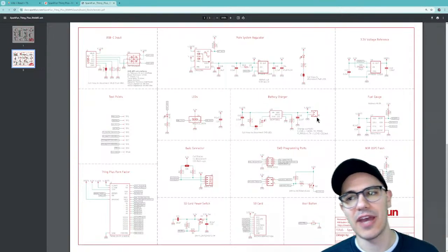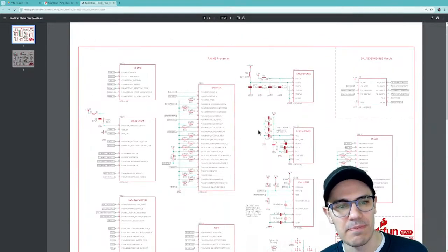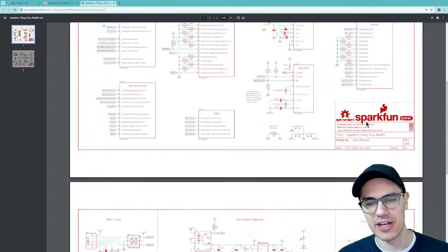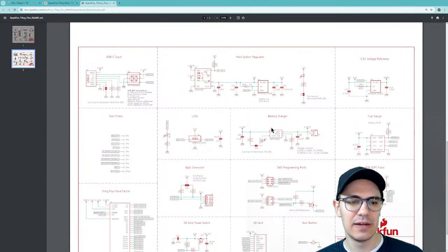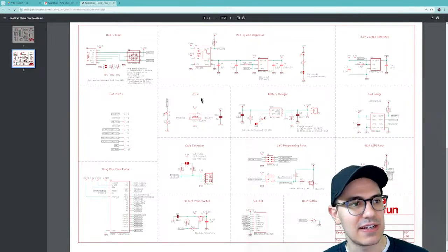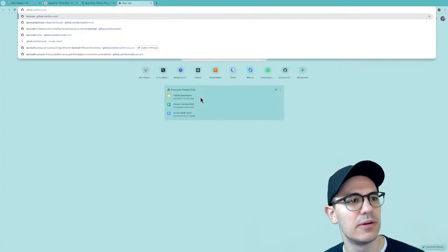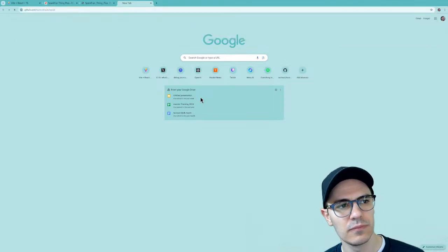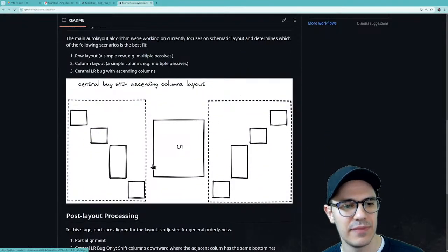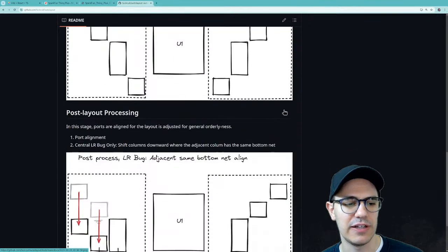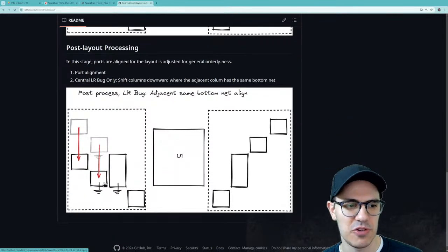So I was like, okay. I think the better thing to do is this is where you run the packing algorithm to organize all these subcircuits, and then you do heuristics for the subcircuits. Because the heuristic I'm doing right now is basically this one where you stack up the components vertically, and then in a post-processing step you make them even.